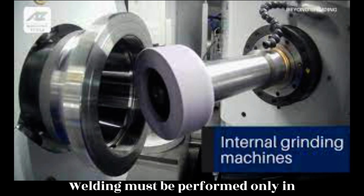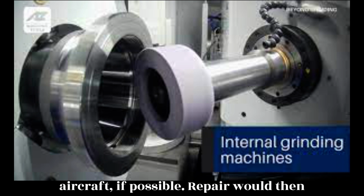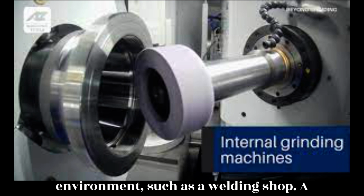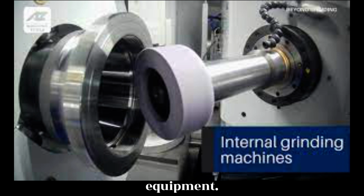Welding must be performed only in designated areas. Any part that is to be welded must be removed from the aircraft, if possible. Repair would then be accomplished in a controlled environment, such as a welding shop. A welding shop must be equipped with proper tables, ventilation, tool storage, and fire prevention and extinguishing equipment.